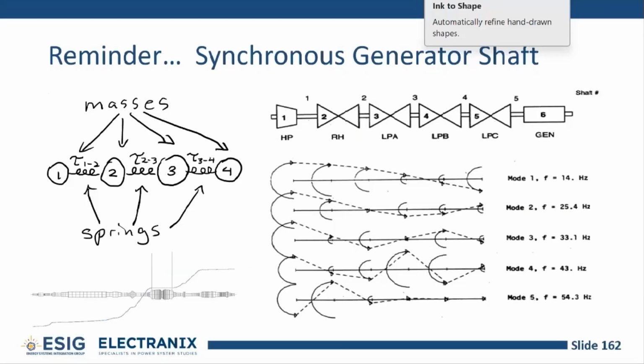Essentially, they made another queue that's parallel to the DISIS, which is their definitive system impact study. And basically what SPP is saying is, you can turn on this high impact large load on a conditional basis with a path to getting firm in their ERAS process or their aggregate transmission studies process. In the interim, you can go ahead and turn them on. You don't have generation to match your load, so basically you're going to be served with non-firm.